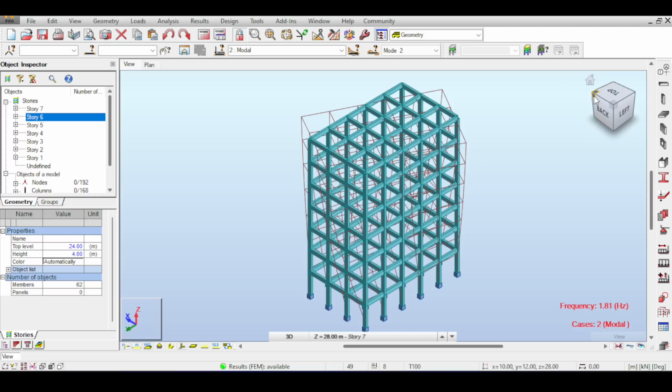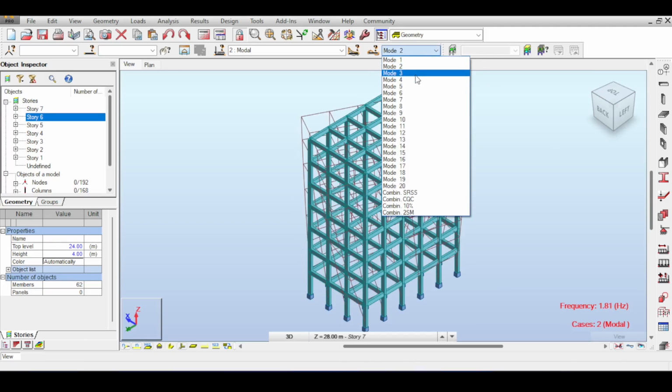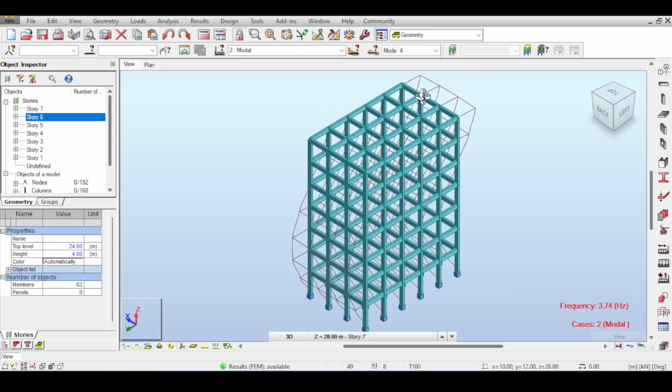Yes, you need to check this out with machinery, to be honest, and I need to make a video for this, but not today. However, what I want to focus on right now is that usually it's not only machinery that causes our structures to vibrate, it's actually earthquakes. I'm talking about most of our structures right now, most of our residential structures. And when it is earthquakes, you can see that earthquakes seldom have a 3 hertz vibration. And even if we have a 3 hertz vibration earthquake, those are rather short and would not be long enough to actually cause some serious problems with resonance.